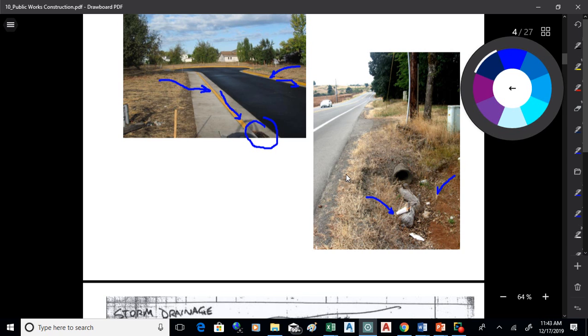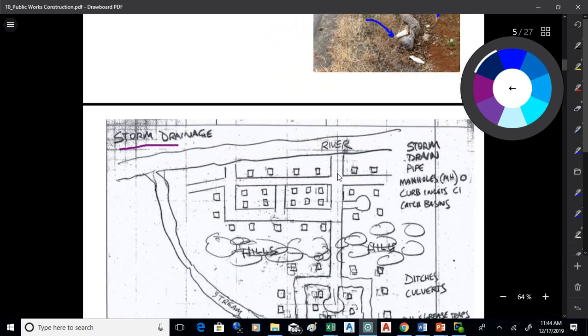Now this road, what it's composed of is compacted gravel underneath. The normal soil in this area would not be strong enough to support a road. So it's excavated and taken out, and then we bring in gravel that's well compacted and strong. Then we put a driving surface on top, generally either concrete or asphalt. Okay, so this road carries the traffic, of course, but then another very important consideration with it is the drainage, which can be handled in either of these two ways.